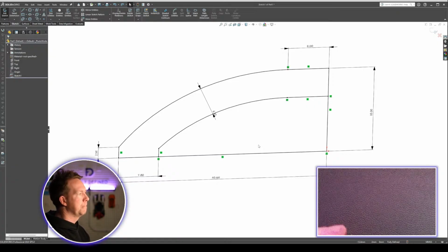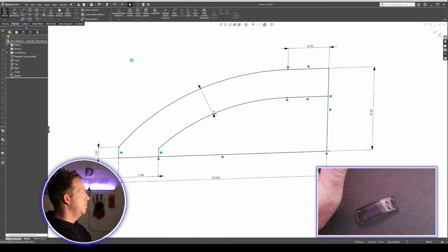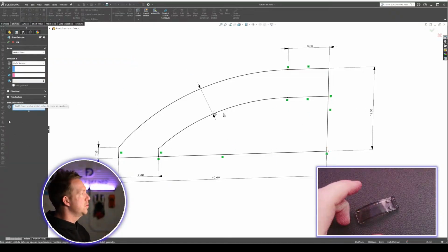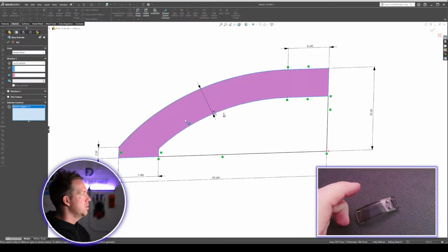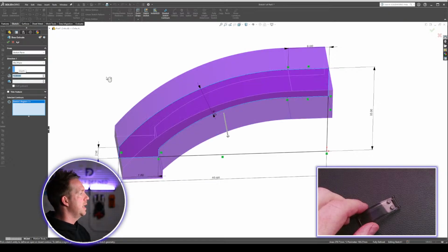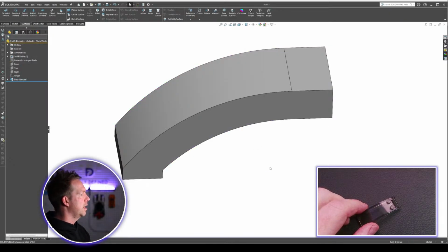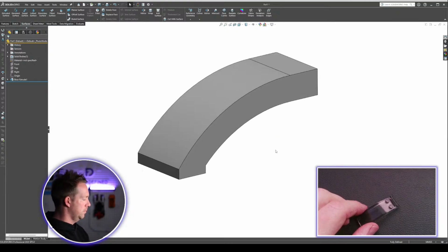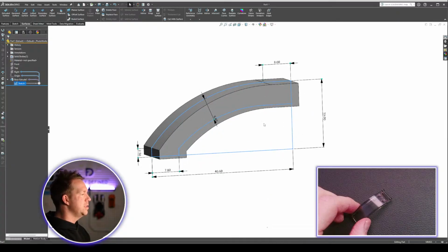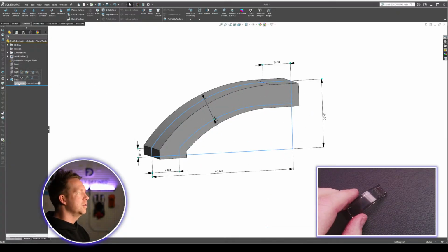Okay, pretty standard. I'm going to press extrude, and because I've got multiple contours there, it automatically asks me for the contour. That's the first selection that SolidWorks brings up. Select the contour, change to mid-plane, 15.8, and OK. Right, and that's just, you know, the information's there, the sketch is all there. Yes, the icon looks different.